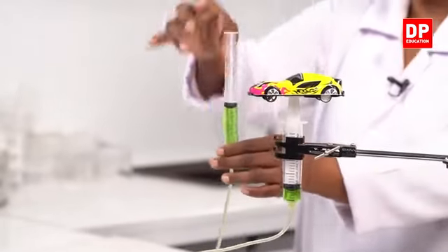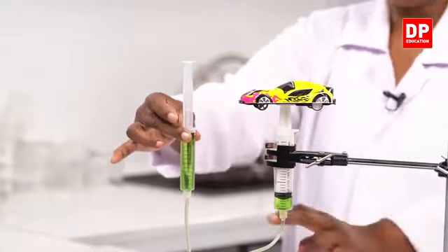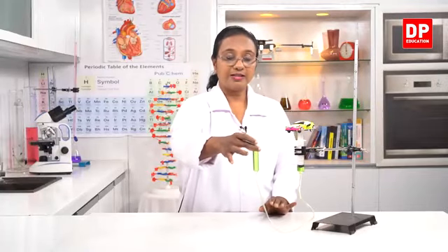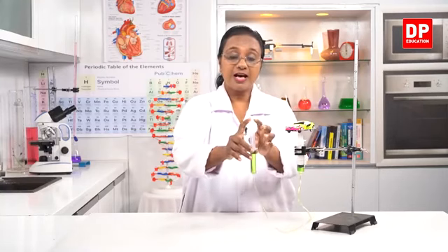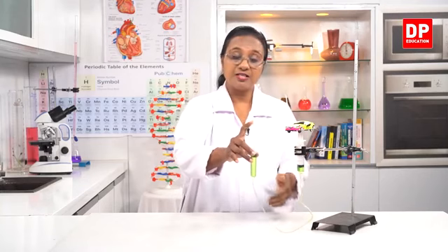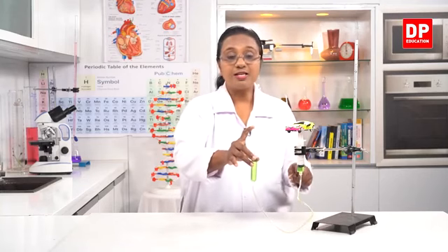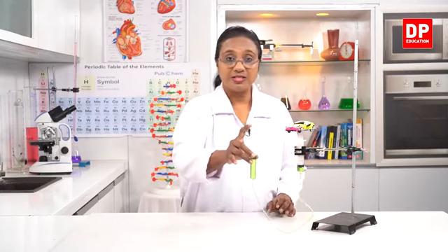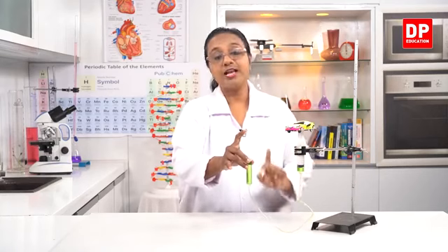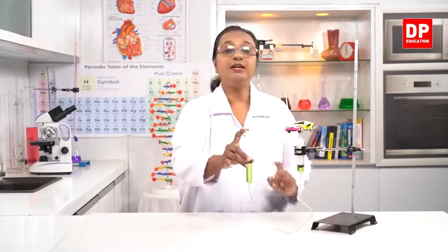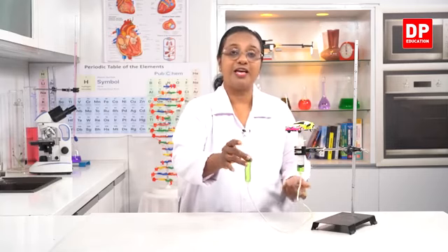Now I have the small piston here. Now you all can see there is a liquid connecting it. So then what happens when I apply a force to the small piston? There is pressure generated, pressure is exerted to the liquid that is transmitted to the large piston, and therefore there will be a force acting on the large piston that will lift the vehicle up or hoist the vehicle up.